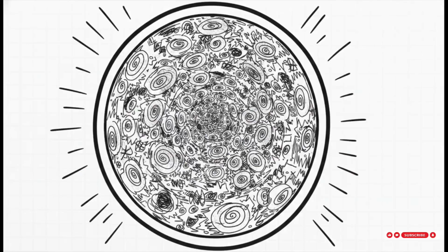63,662. Now, here's the so what of that result. Remember those magic thresholds we talked about? Because 63,662 is way past our 4,000 limit, we know with absolute certainty that this water flow is wildly turbulent. We've got cross currents and eddies mixing everything up inside that pipeline.